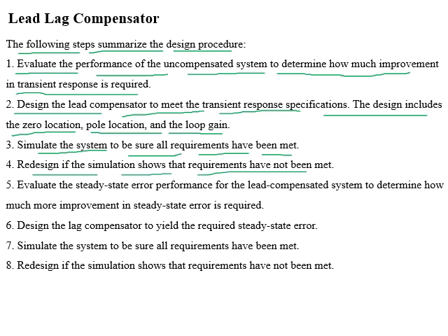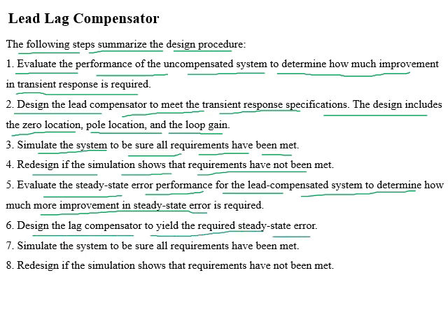We will evaluate the steady-state error performance for lead compensated system to determine how much more improvement in the steady-state error is required. After this, we will design the lag compensator for improvement in the steady-state error. Then we will simulate to make sure that all requirements have been met. And we will redesign if required.